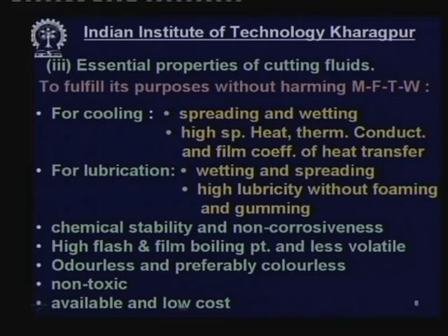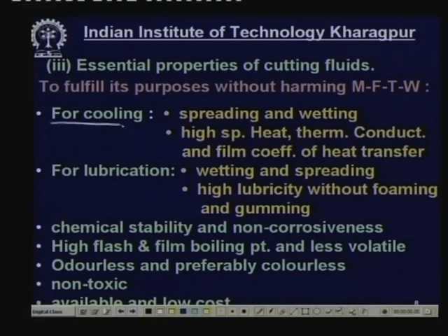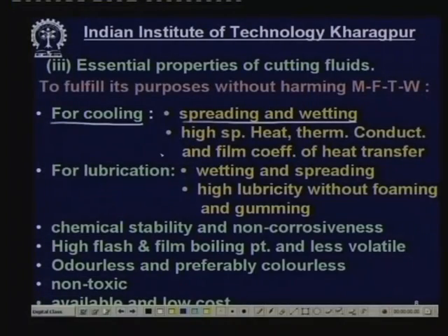The main properties it needs for cooling purpose are spreading and wetting. First of all, the cutting fluid should spread immediately over the tool surface and job surface, and it should wet the surface, otherwise it will not transfer the heat. Second, it should have high heat carrying capacity, that depends upon high specific heat, high thermal conductivity and high film coefficient of heat transfer. These three values if high, then the heat carrying capacity will increase, and you know water has got all these properties, and this is essential for the fluid.